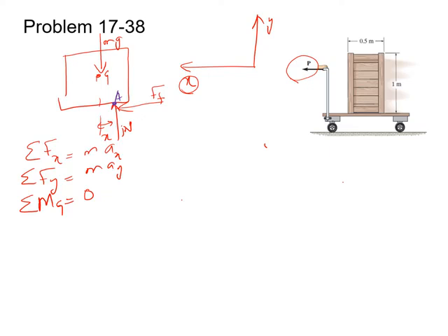So the third condition can also be written in such a way that the sum of the moments about point A equal to the sum of the kinetic moments about point A. So for condition 3, we can use any one of the third conditions to find the moment about point A or to find the moment about point G to solve for the unknowns.